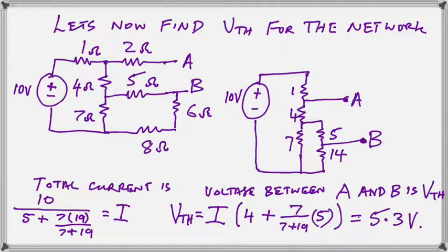And the reason why we can remove the resistor is because we are measuring a voltage. No current is flowing, so the resistance will not alter it. In other words, the 2 ohm resistor would have the same voltage at both ends. So we simply take it out.